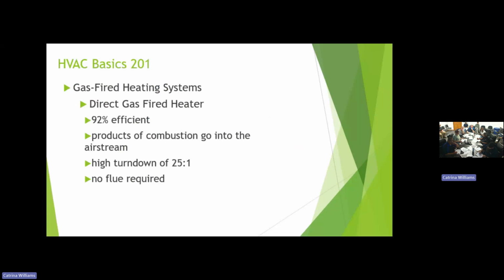And also, if you don't start out at high fire, say you ordered a burner that is 900,000 BTU, but the burner has the capability of going to 1,100,000, you're not even starting out at high fire to begin with if you're only going to get 900,000 out of it. So that means 900,000 down to what the level is at 100 or 1,000,000 becomes your new low fire. But this is the maximum we get out of it.